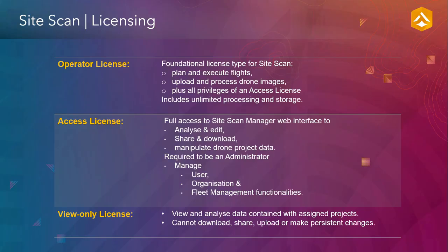And then there is the view-only license. Now, the view-only licenses are virtually unlimited. You can supply the login to as many people as you like. You can do virtually any of the analysis that the access license can do, so some of the profiling, the volumetric calculations, but you can't make any changes and you can't download any data with it.